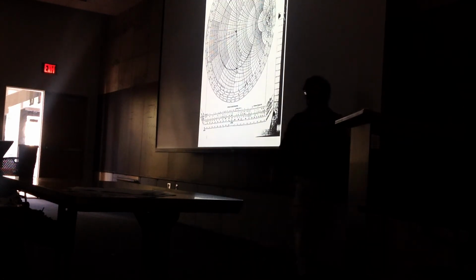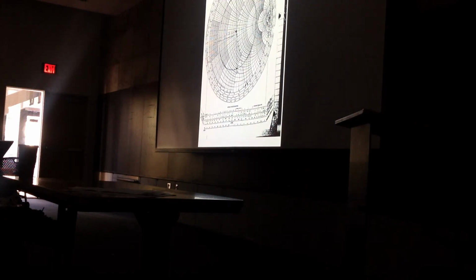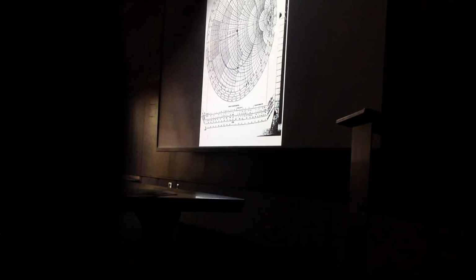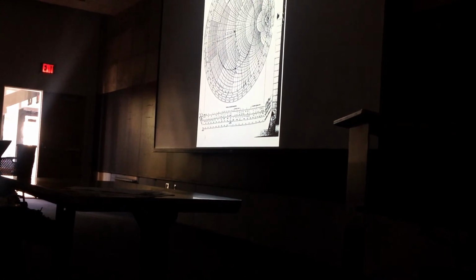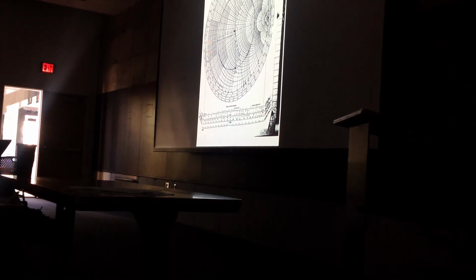So now, how do we determine how much wavelength distance you need to travel? You take this point here, then you read from your Smith chart the wavelength. The wavelength here is about 0.178. And looking at your Smith chart, the radial line for this point intersects the circle at about 0.115.